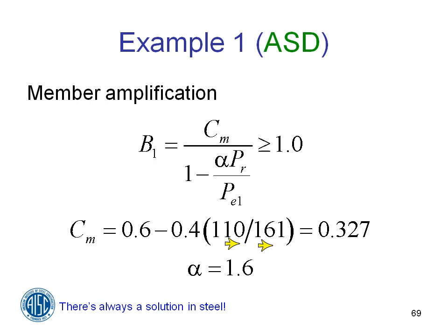Question, are these first and second order effects considered that you know of? Are they considered in commercial software programs? Yes, but the real key is how does your commercial software do it? Now, I'm guessing that if you have a very old version of something, it may not. But if you have a modern version, as far as I know, all of the modern commercially available software that is used in the building industry has some way of accounting for second order effects. You need to find out what method they use and make sure that you're comfortable with that.